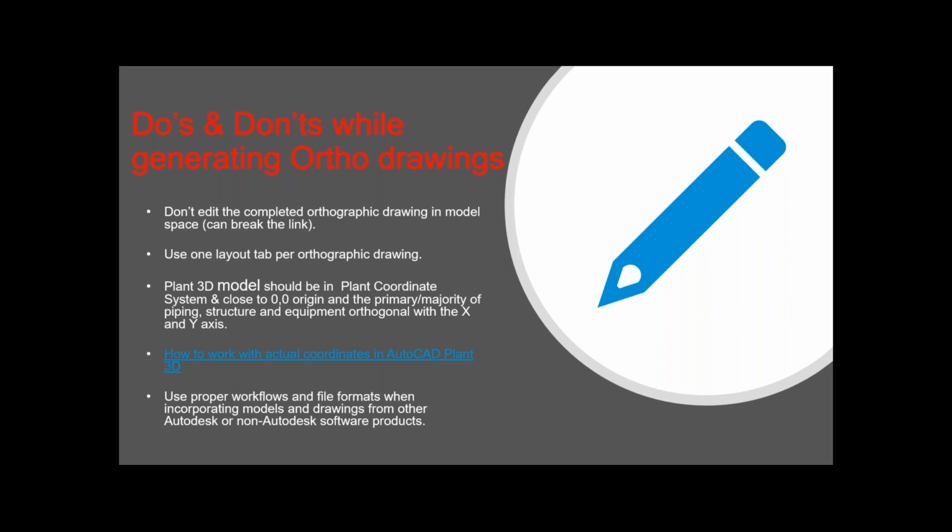Another key thing that we want to highlight, which is one of the common issues we see customers facing when they generate ortho, is when you bring in any external reference drawings, be it an AutoCAD external reference drawing or a structural drawing from Advanced Steel. When you're bringing it into your Plant 3D model for ortho generation, respect the plant coordinate system and keep it at the origin.